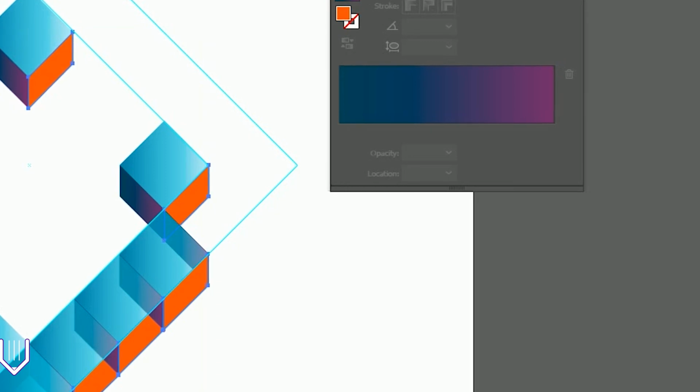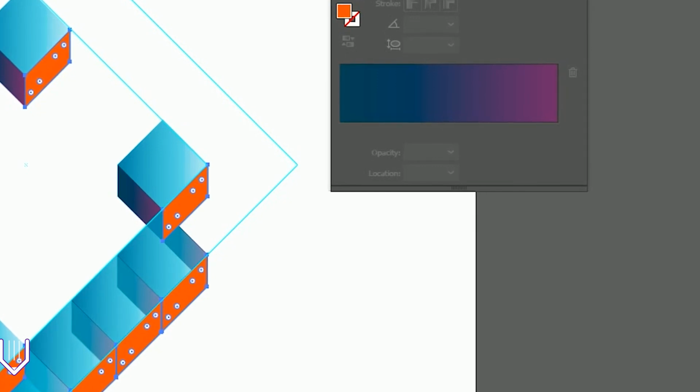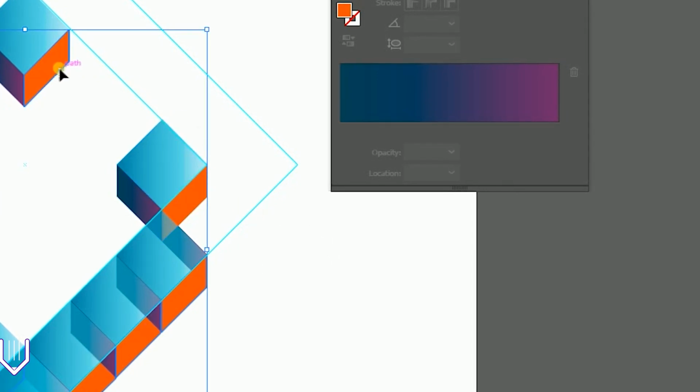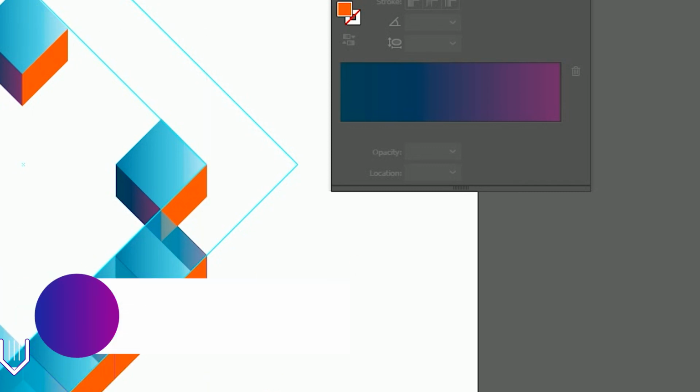orangey sides. In order to do this, again, click on these orangey sides and let's go and bring up them to the front. You see? It's bring up also this 4 that should be inside. I don't want it to. I want to deselect this, and this as well. So simply hold Shift key and deselect these guys. You see? I deselect them all. So next, bring up them to the top of your layer stack.